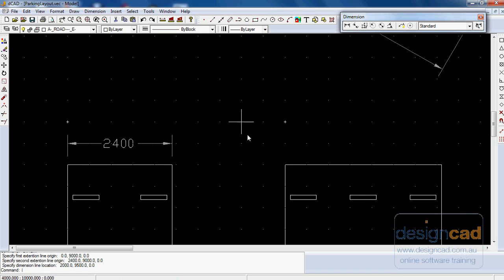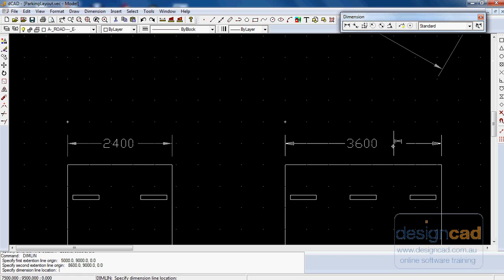from the edge. It becomes more obvious when we pick our dimension tool and dimension this wider car park for disabled folk. And now can you see I'm lining those dimensions up just with the clicks because the snap is on. So you take the snap off with F9 and you take the grid off with F7.